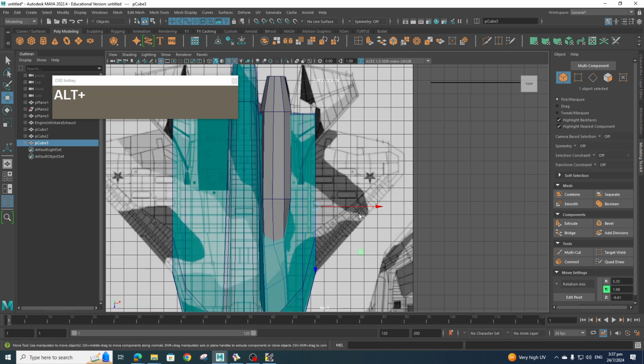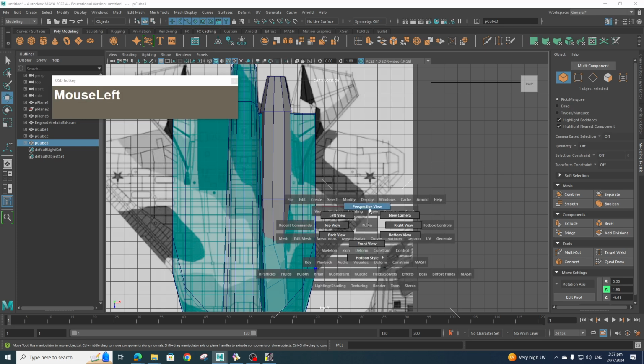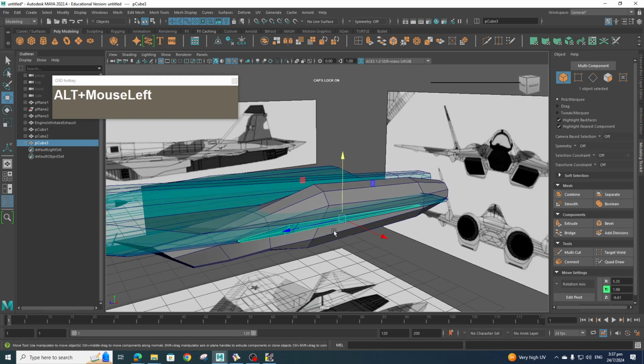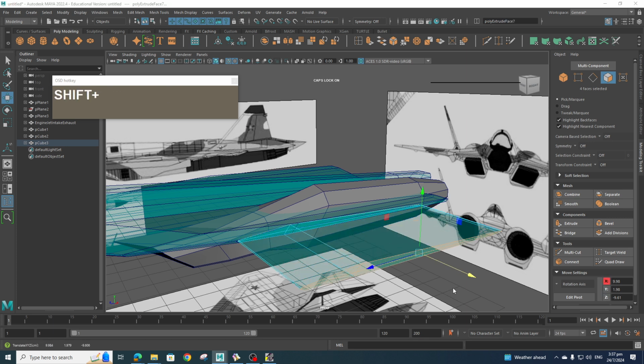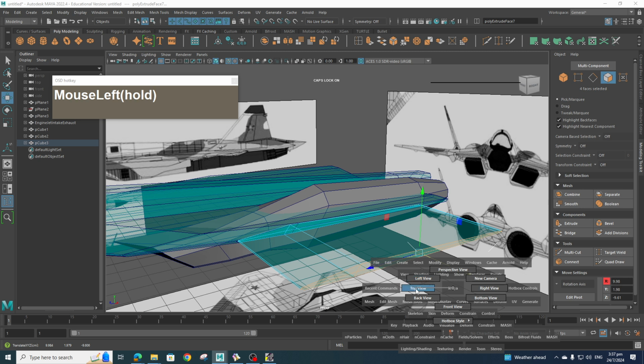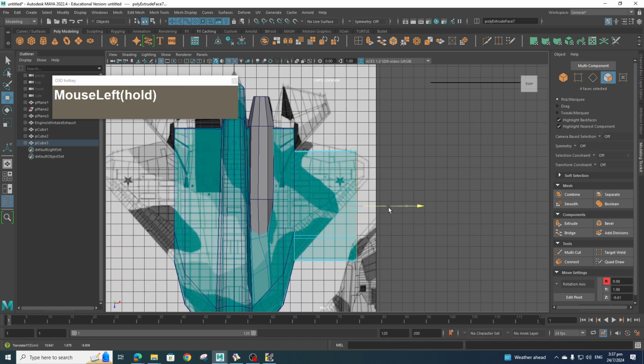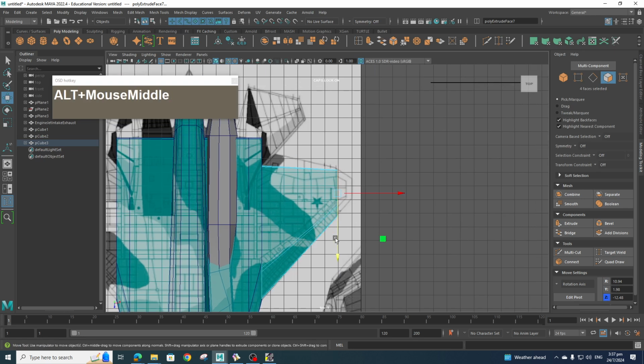Okay, so now I can extrude this out. Let's go to the face and select all the faces. Then I'm going to extrude out the wing. Let's go to the top view and see. Continue to extrude until... Okay, again there's another slight crank over here, so I will scale this down. Uniform scale, so that means there's going to be a taper. Okay, while the face is still selected.